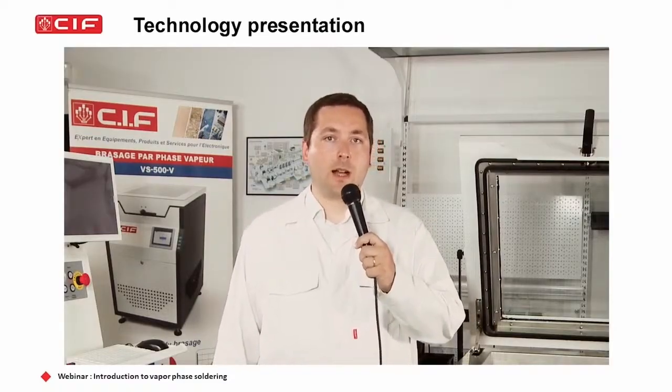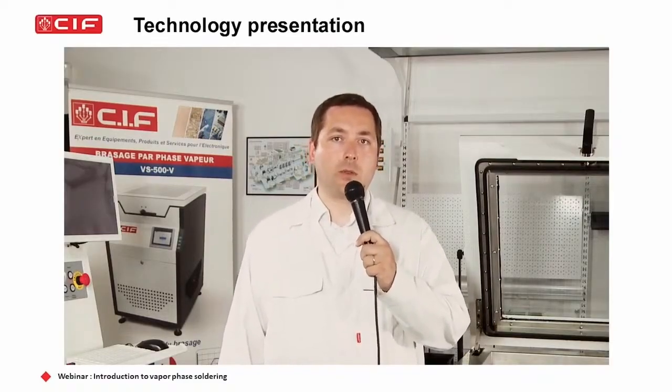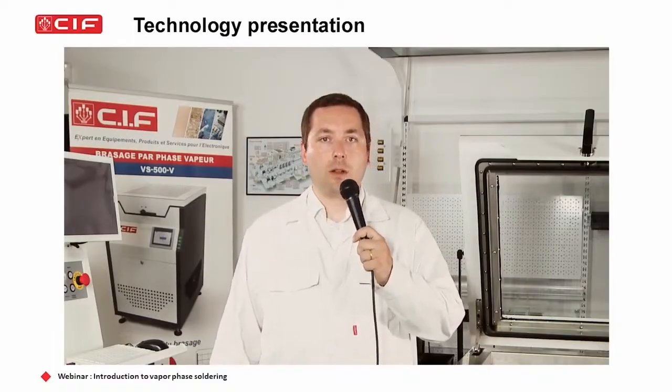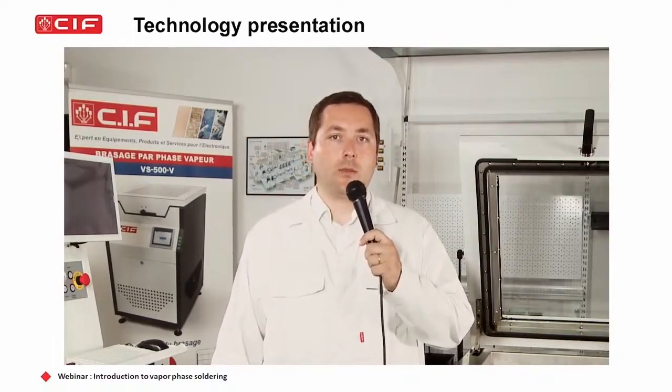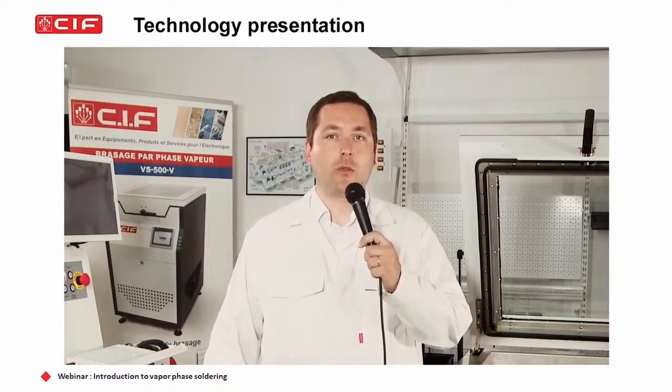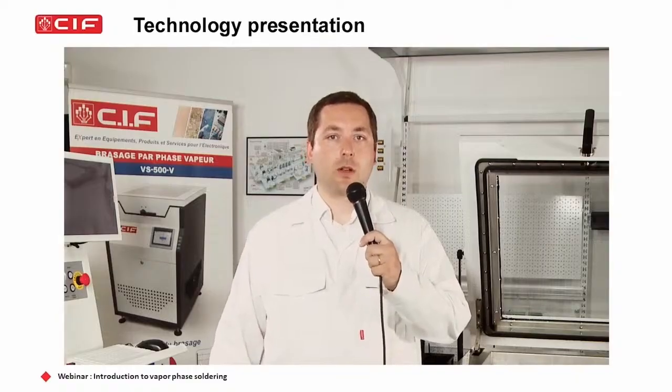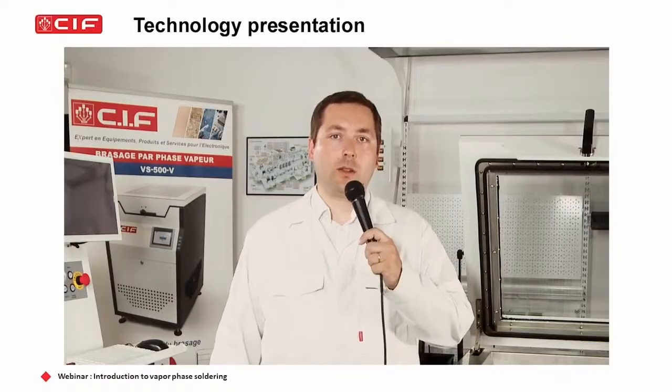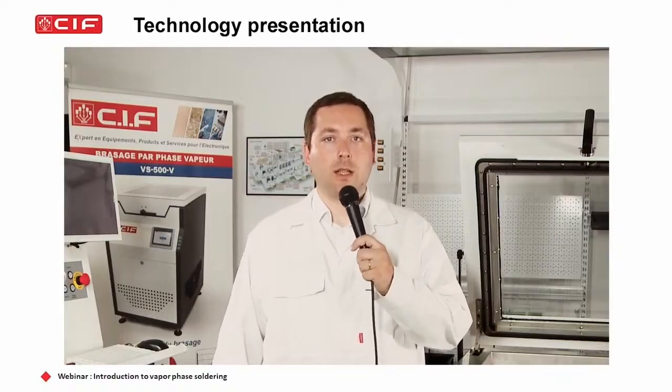For information, the IPC recommends that you need to be able to control the amount of voids, meaning to have an average, same amount over your process, having a good repeatability, because this means you have control over your process, which we do have here with the vapor phase technology.